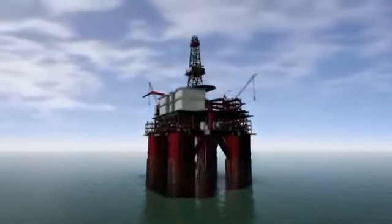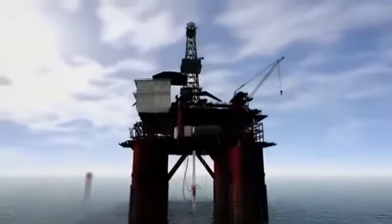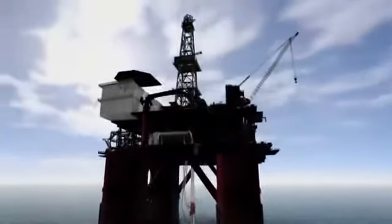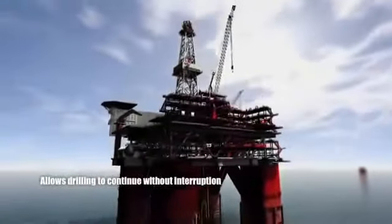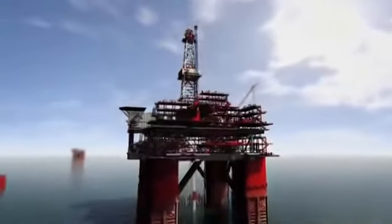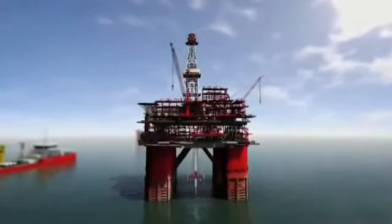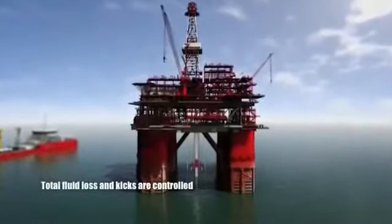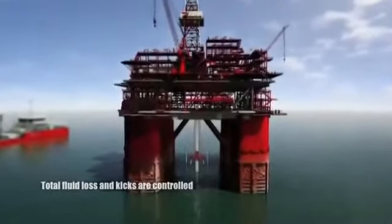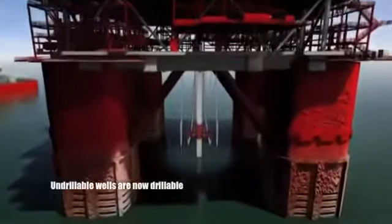In these extreme situations, where loss circulation techniques don't work or are too expensive, pressurized mudcap drilling allows drilling to continue without interruption. Because pressurized mudcap drilling is engineered to inject all the drilling fluid, cuttings, and produced gas into the formation, total fluid loss and kicks are controlled. As a result, difficult or previously undrillable wells are now drillable.